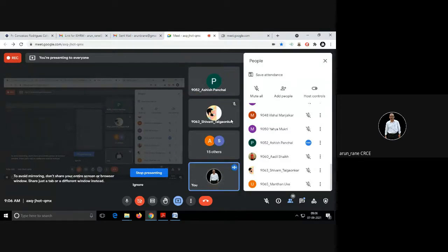What will be the piercing die size? 20.2. Who was telling 19.8? How will that be? How will your 20 punch enter 19.8? Yes sir, we have to add. Okay, if you want you write down this. Simple example. Suppose this is a hole, 20 dia hole. So piercing punch size will be 20 and piercing die size is equal to 20.2.